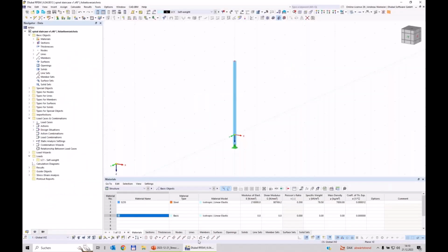And here we start, or let's say we define a level where we want to place it. And for this, I use my working plane, and it's, let's say, 8.5 centimeters above this point. I want to open the topic, how you can move your working plane 8.5 centimeters upwards.